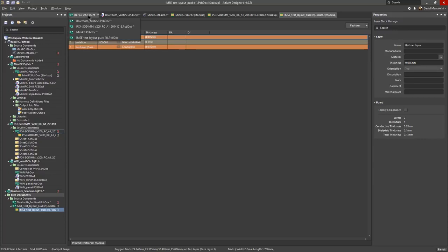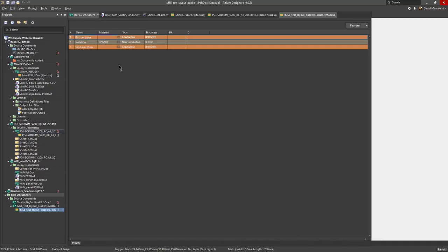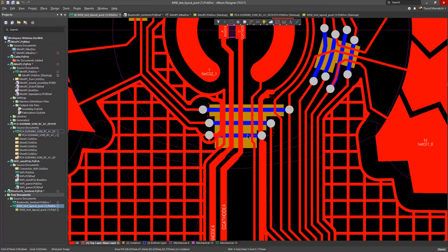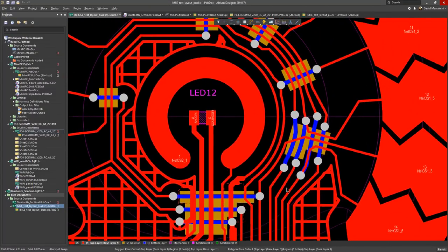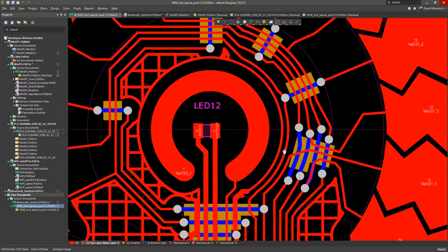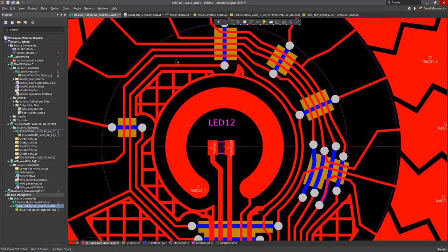If we look at this design, we have these patches between all crossovers, and that's what distinguishes a printed electronic layer stack, because traces that overlap constitute a short, and therefore they need to be isolated. A typical PCB doesn't need to do this because the layers are already separated and isolated. And that's the other thing Altium Designer 19 does.